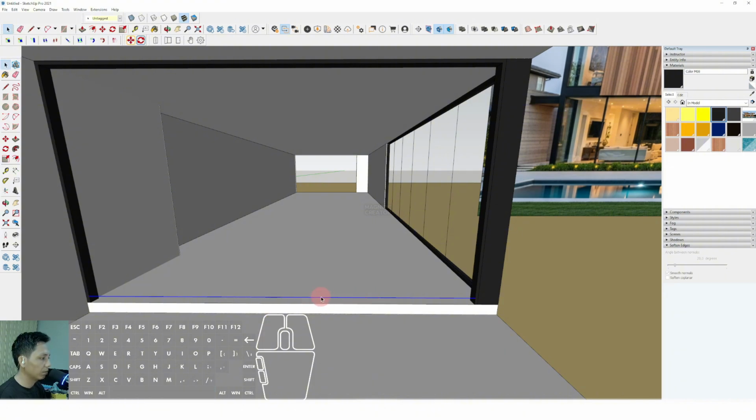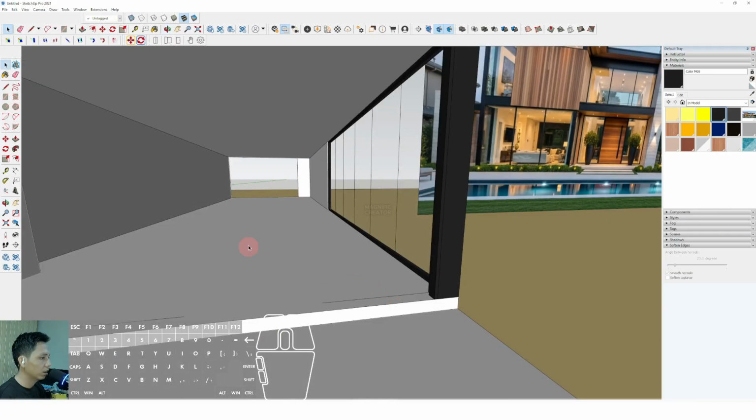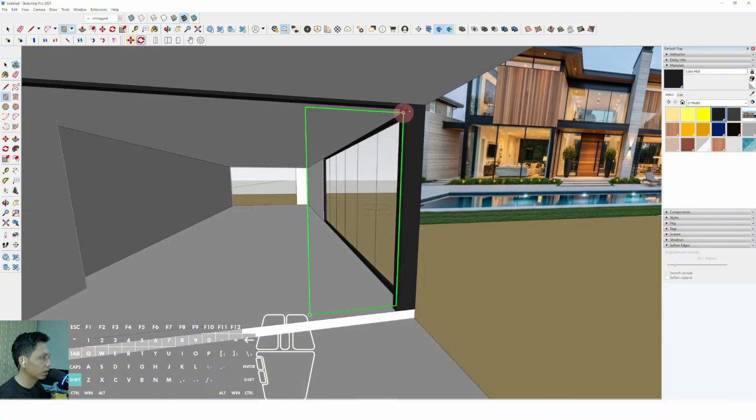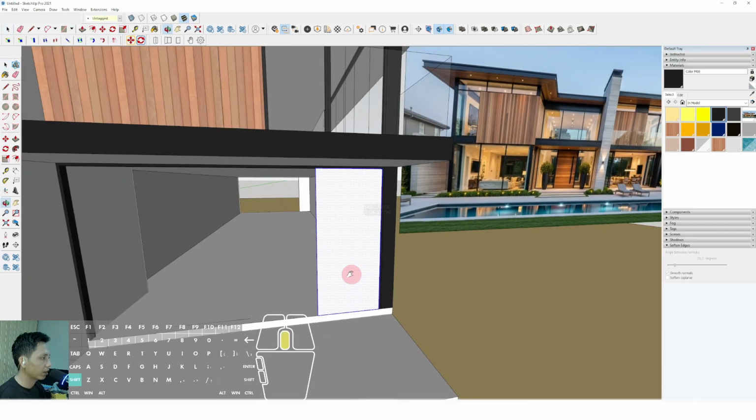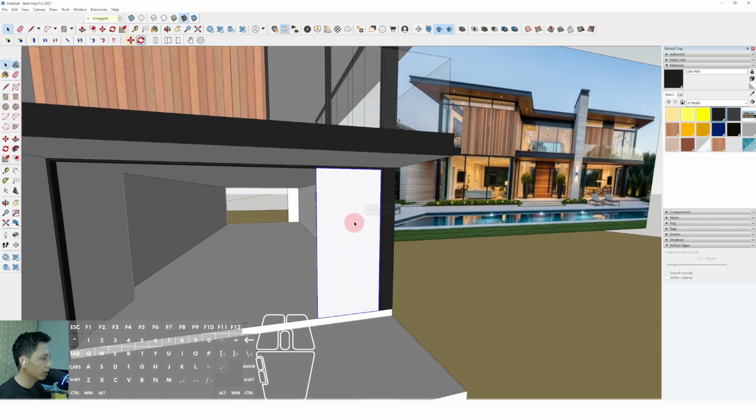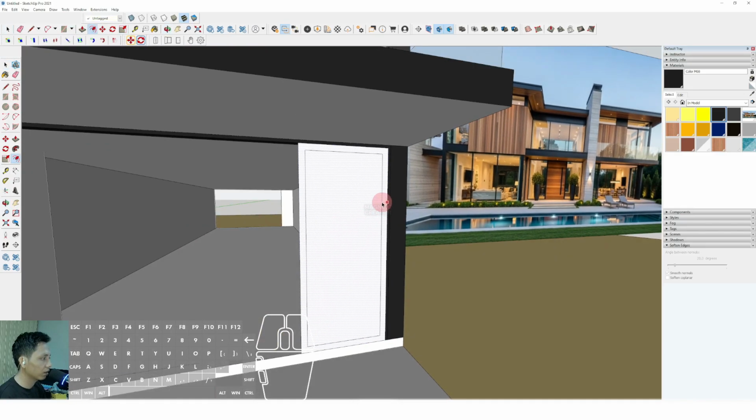Okay, perfect. We can delete the other line first. We can select rectangle, click from this point until this point. Then we can scale this one. Now we can click the surface and offset it inside around 50 millimeter and enter.